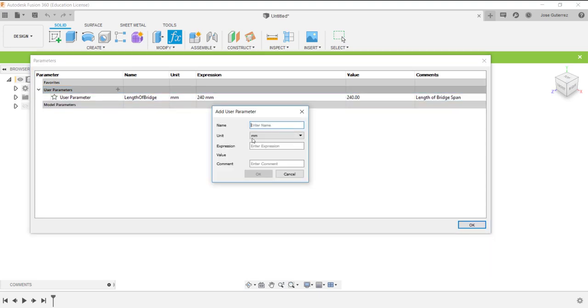We're also going to do thickness, and this is going to be the thickness of our balsa wood member. You should actually measure your individual members, but one of the ones I just measured was 3.175 millimeters on average. And so this is the thickness of balsa wood.